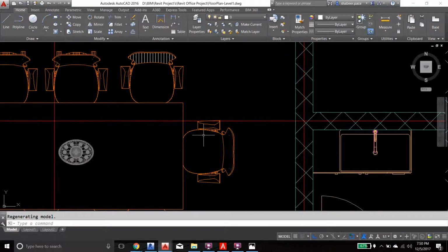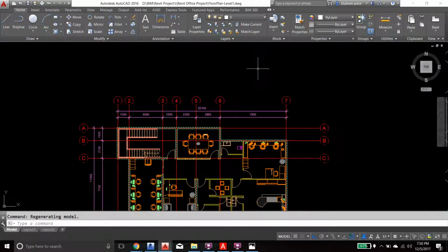So sometimes what happens is, as in the case of what you're doing, you will get a block from somebody and you want to use it at one place, but at the other place you want to use the same block with minor changes. So you will not disturb the original block. First of all, take this block and keep it in an open area, a blank space somewhere, and explode it. But you should be very careful when you're exploding. Sometimes when you explode, the inside objects, annotation, text and all this, will get disturbed. So be careful when you explode to see that the block is looking the same, visibility, everything is the same. Then make your changes and make the block again, and then you can apply it in the places.